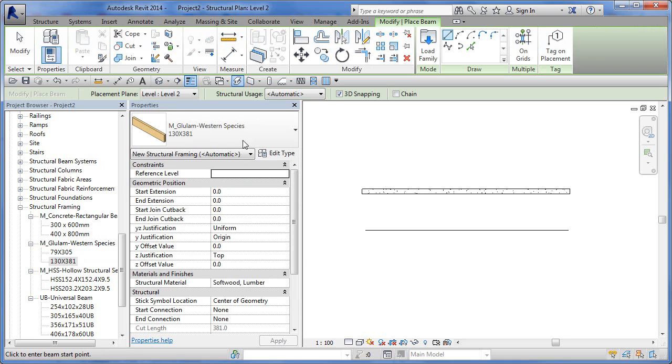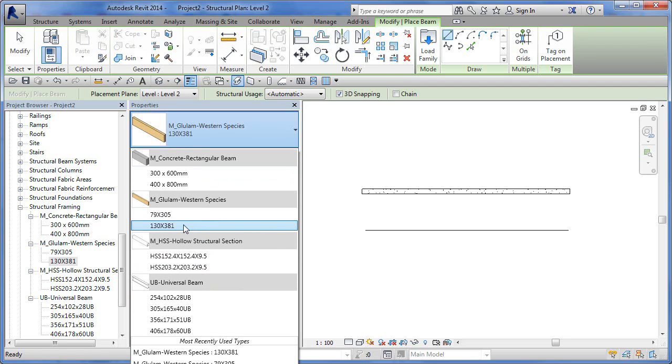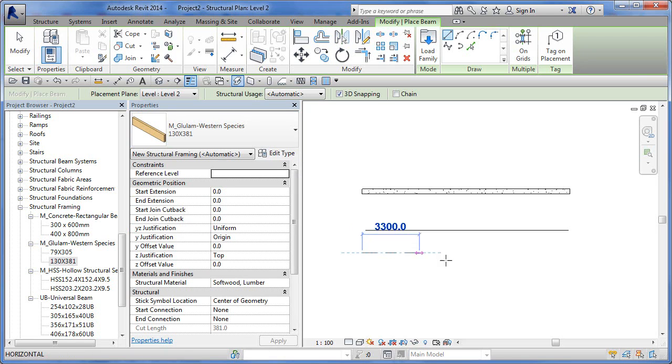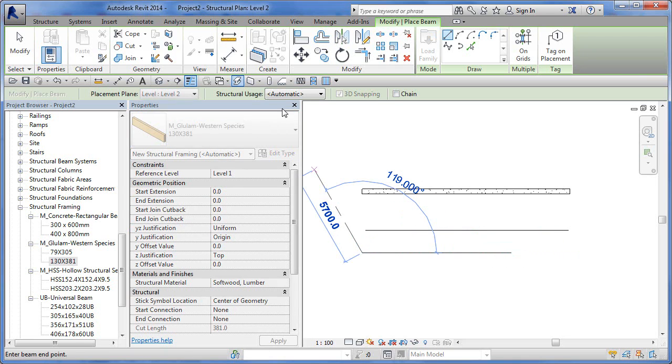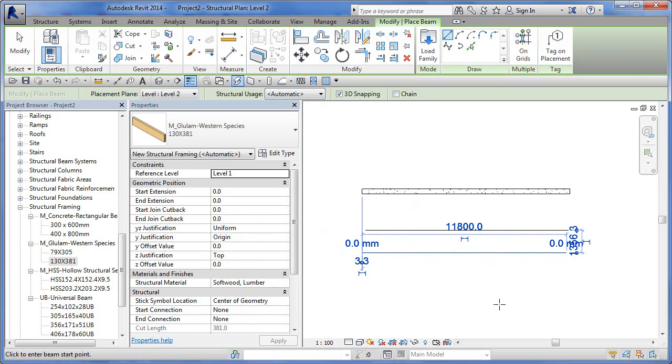So let's pick the bigger one, and let's just drag it in. We can do that, or we can start the beam tool off of here and then pick it off of our list over here. It's up to you. Then click. Again, we're going to talk about all these options up inside of here. I'm completely ignoring those for a reason right now. Click, and then I'm done.